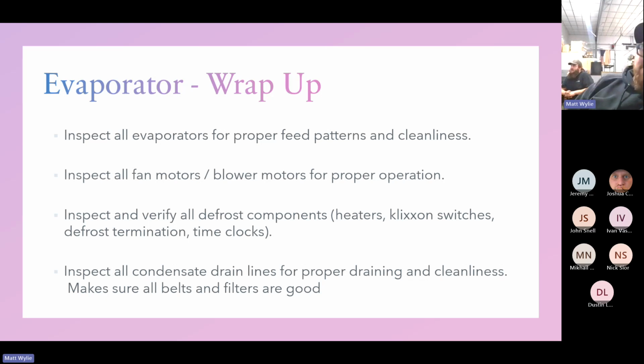Evaporator wrap up. Inspect all evaporators for proper feeding pattern and cleanliness. Inspect all the fans, motors, blower wheels, proper operations. Inspect and verify the defrost components, heaters, klixon switches like Dustin was saying, defrost terminations, time clocks. Back to what Dustin and John were saying, if you get to those walk-in freezers, you open the door and there are those little droplets on the ceiling or all over the place or on the product, most likely you're looking at the defrost termination or fan delay or drip time not working properly.